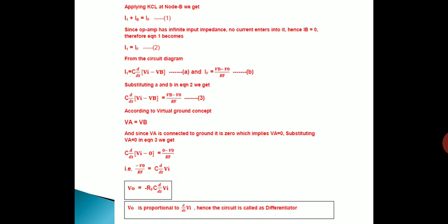Here Rf is constant, C is constant, hence the product of Rf and C is called the time constant of the differentiator, and the negative sign indicates it is an inverting op amp configuration. Hence V0 is directly proportional to d by dt of Vi, that is the derivative of the input. Therefore the circuit is called a differentiator.